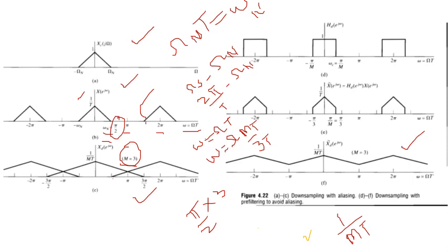According to the equation, whenever we have something like this, our signal will expand in the spectrum. So what we are doing is using a decimation filter. The decimation filter is in the discrete domain, so it will repeat itself: we have copies at 0, at 2 pi, at minus 2 pi, and the limit of the decimation filter will be pi divided by m. Here m is 3. So we are going to pass this signal X(e raised to the power j omega) through this filter. Obviously pi by 2 is greater than pi by 3, so it will go outside.